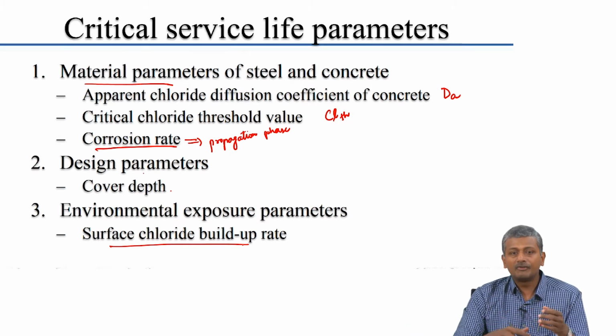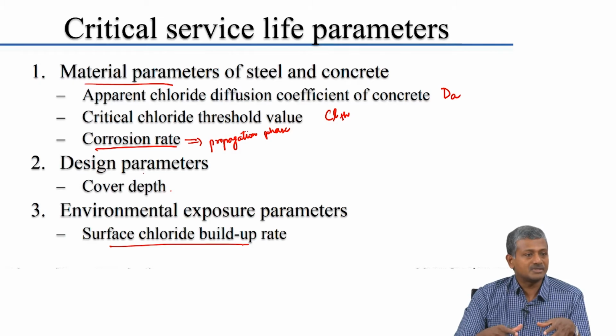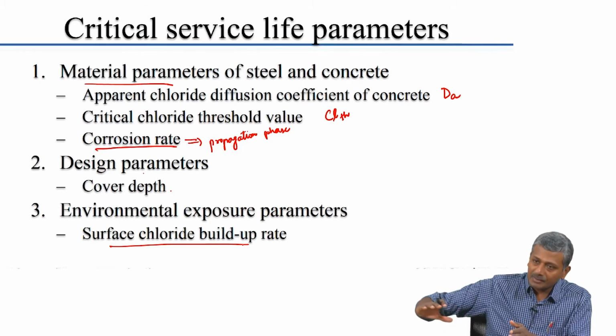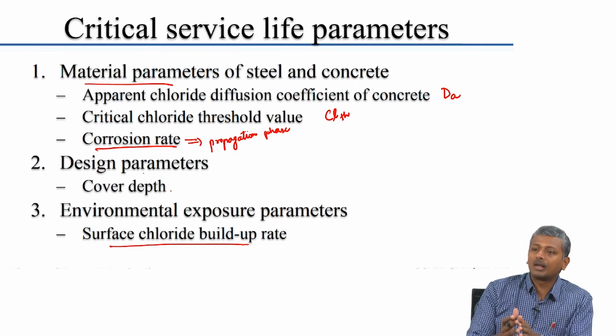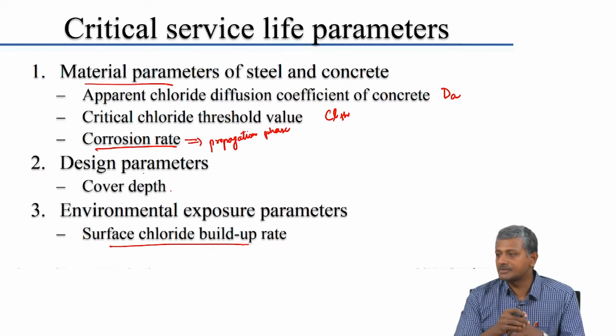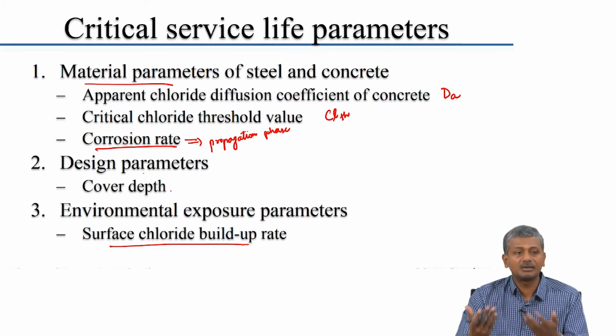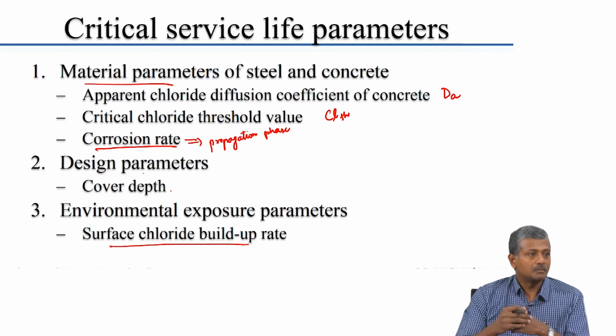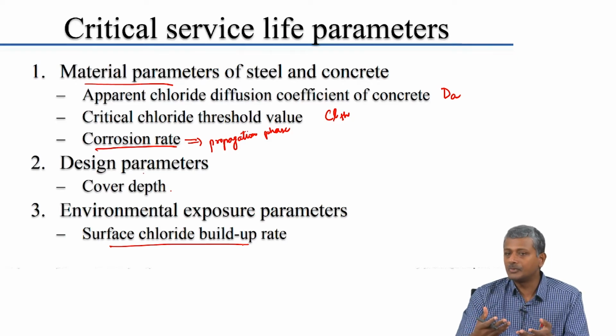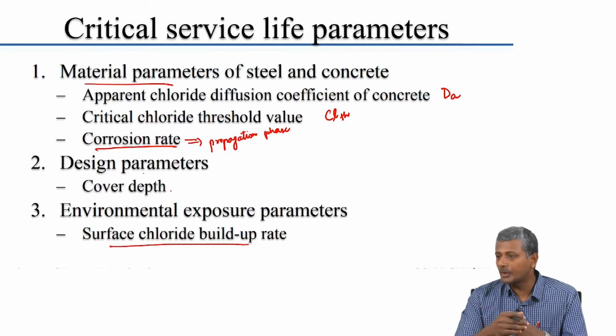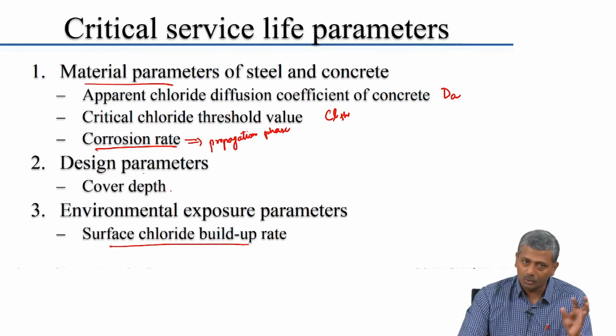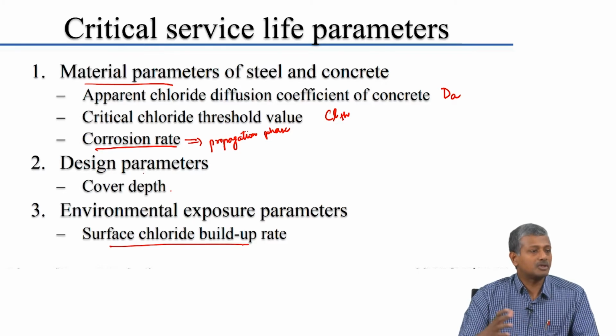beginning. If your concrete is sitting inside a chloride infested soil, it will take some time for the chlorides to actually build up to a large concentration on the surface of the concrete, which will lead to an increase in the level of diffusion. But this state of very high chloride concentration at the surface may take some time to actually happen. So, some of these models actually account also for the time it takes for that build up to happen.